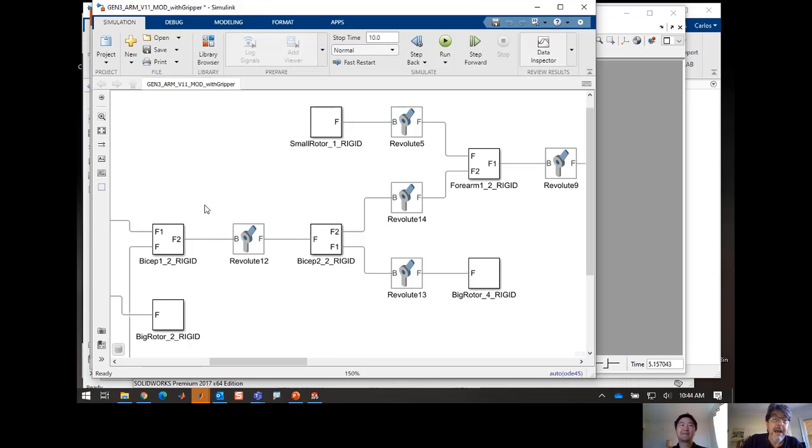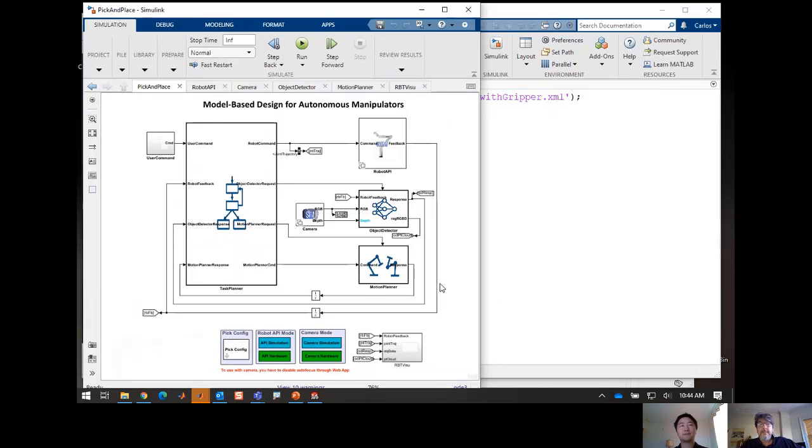But now that you have a dynamic model, you can go into the individual joint connections, attach electric motors, apply torques on the appropriate joints, and design your control algorithms there. Does that mean after I create a model of this robot, I can then program this model? And then when I want to deploy it to hardware, do I need to reprogram everything again?